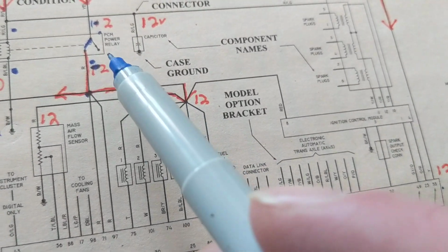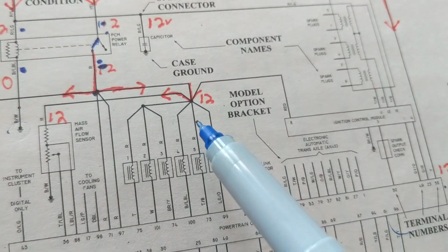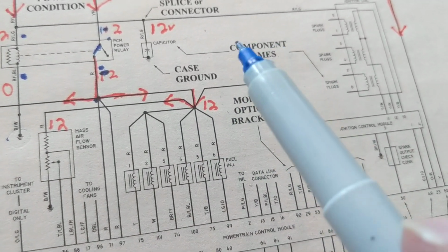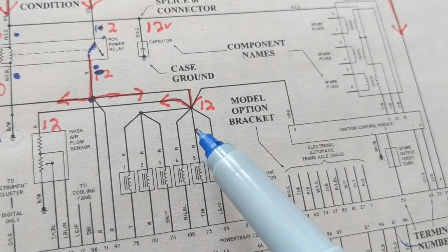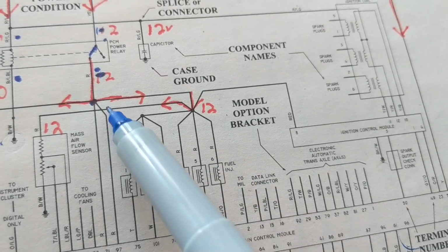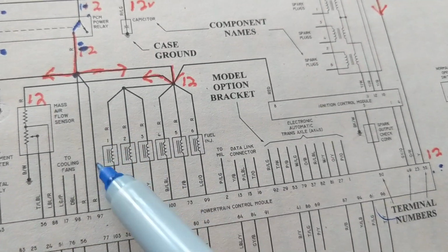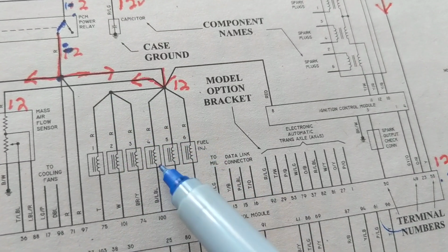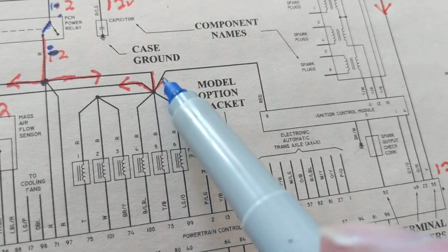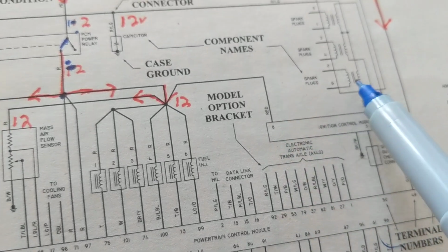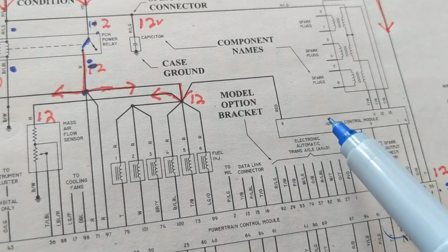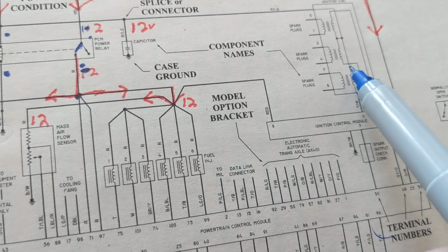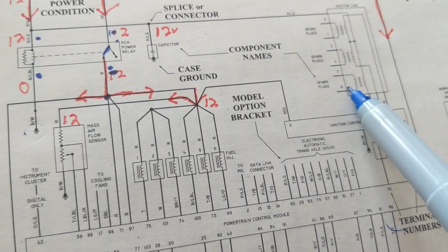Yesterday, I made a video about a common bus line. Whenever you see all these nodes, these splices, one thing should go into your head: this is a voltage supply line. 12 volts here, 12 volts here, 12 volts here, 12 volts to each and every single fuel injector. 12 volts also to the ignition control module to give you the spark. This gives you the fuel out of the fuel injector. This gives you the ignition coil to give you the spark.